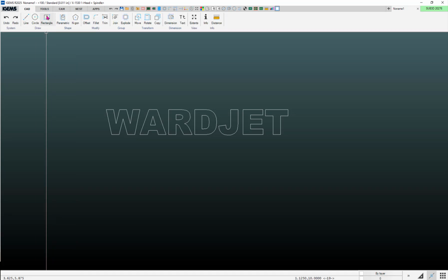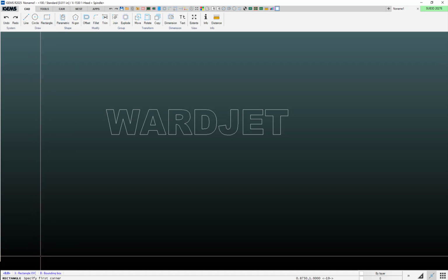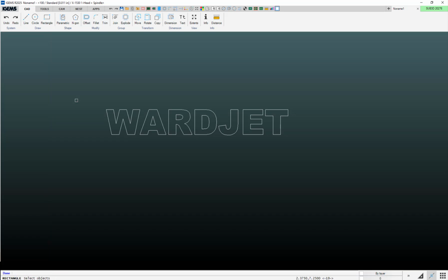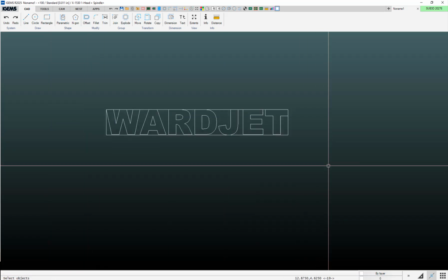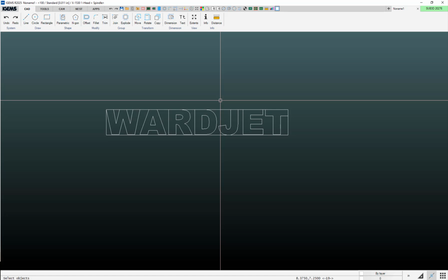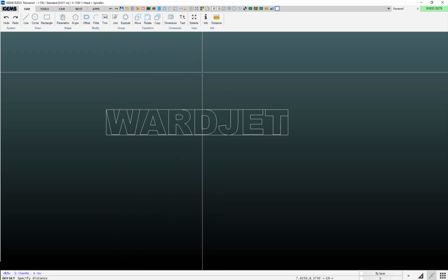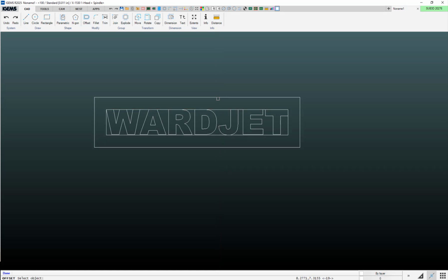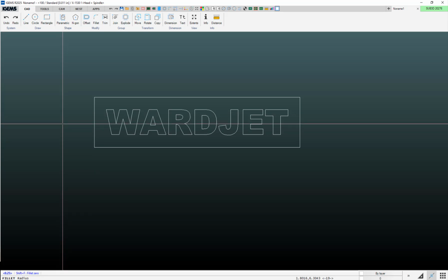And then I'll just draw a quick rectangle around here using the bounding box option. And I will offset that. Let's see, 1/2 inch. Click on that, do that, hit escape, hit delete. And let's put some rounded corners on there with the fillet command. Prompts us for radius. I'll hit enter for the 0.25.